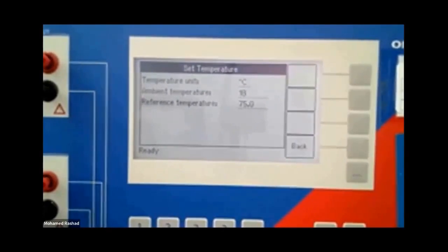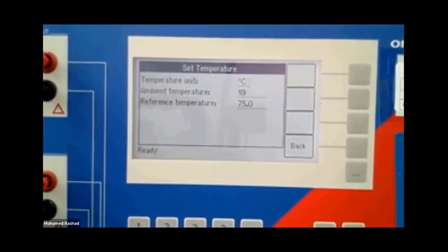They tell you that this resistance equals a certain value at 75 degrees Celsius. This means that my calculations, which include the specific resistance of the material, the length of the conductor, the cross-sectional area of the conductor, the number of turns, and everything related to the manufacturing of this conductor, should not exceed this resistance value at 75 degrees Celsius.